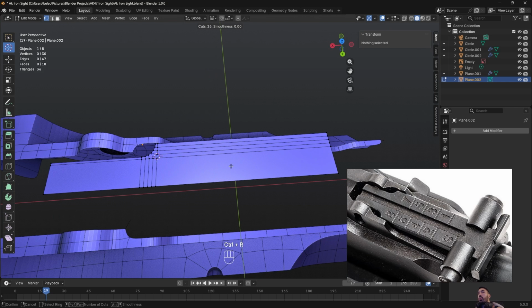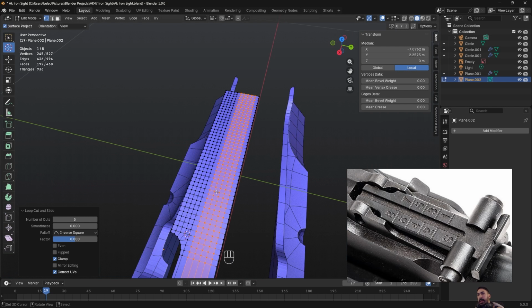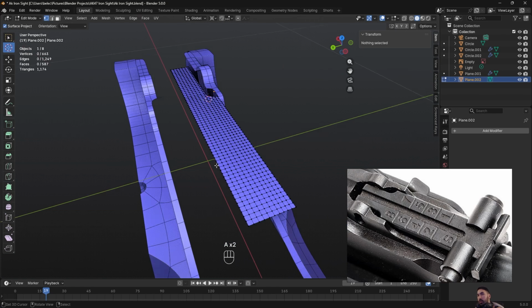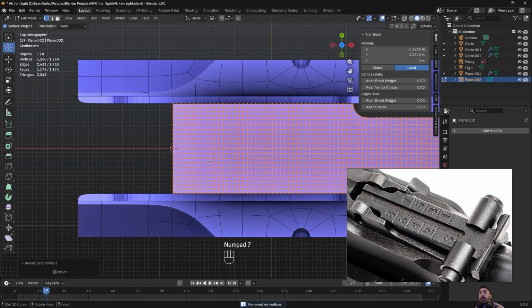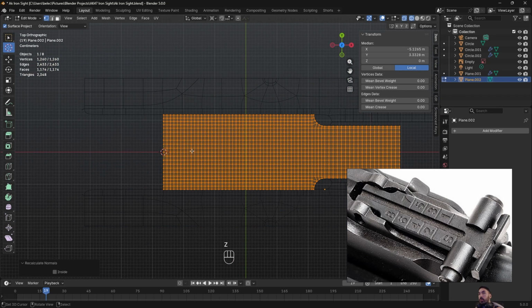So in a perfect world where we employ geometric consistency all the way, I add like 42 loop cuts here, then I add something like, I don't know, what's that, 5 loop cuts right there, another 20 loop cuts down here to turn everything into little squares. And then once we do that, we can mirror this to bring it over to the other side, and those beautiful little squares are going to allow us to create what we're trying to create, which is the following.